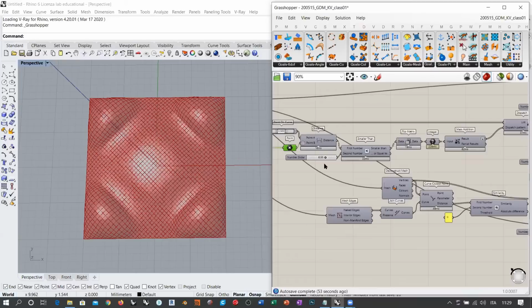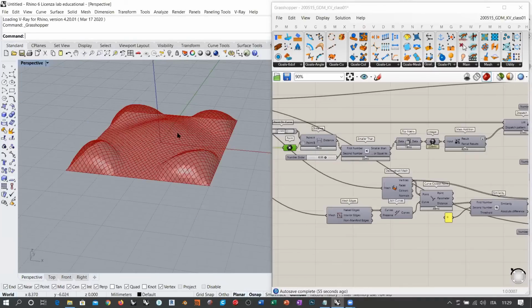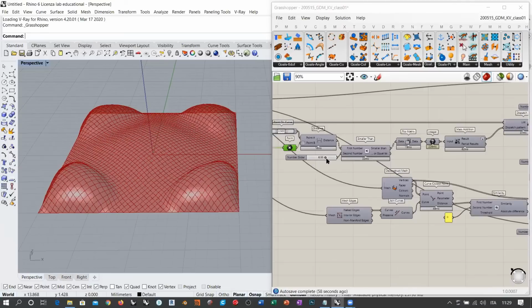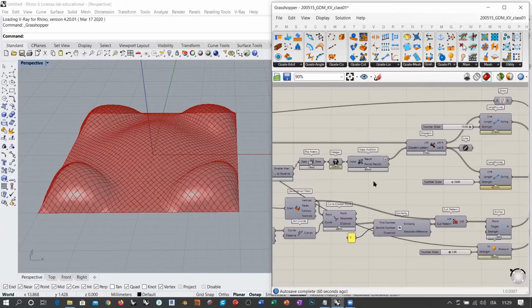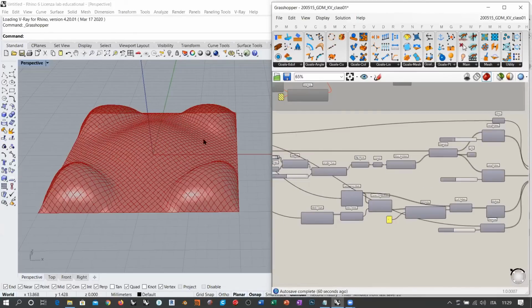Now this is another parameter that I cannot edit on the fly, because this parameter here would affect the amount of elastic edges and the amount of rigid edges. So this is a change in the geometric system for Kangaroo. And you cannot do this on the fly, because if you do this, Kangaroo is no longer able to sort the elements properly.